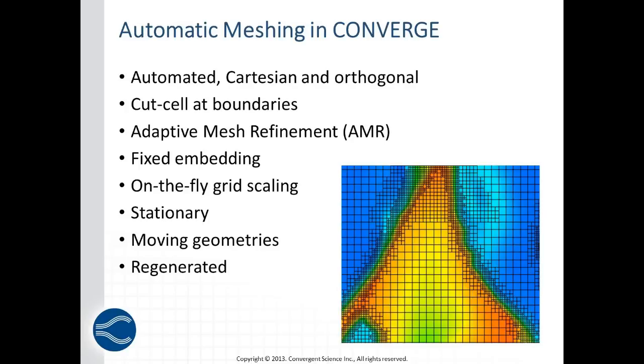So if you have areas of high gradient, like let's say I'm looking at right here, you start off with a baseline mesh size, or a base mesh size, and then that is adapted automatically based on gradients. Perhaps those are gradients of temperature or species concentration, but they could also just as easily be gradients of velocity, shear, or swirl, or things like that.